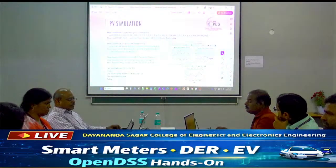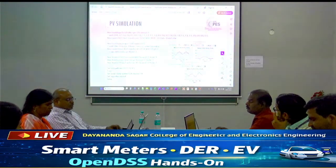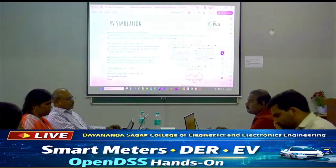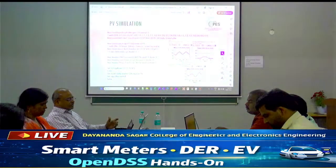So you put the monitors, and then we say mode is daily, number of steps is 24, step size is 1 hour. Even though we have given this as 1 minute, for the load we have given only 1 hour. If you don't give it, it will automatically interpolate.